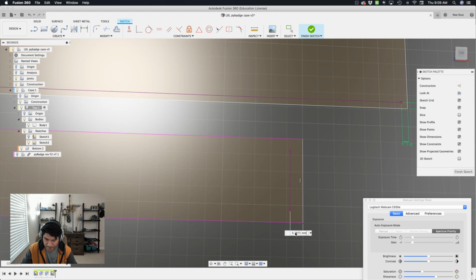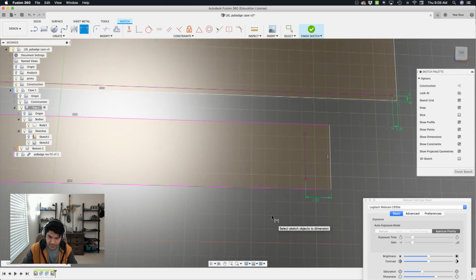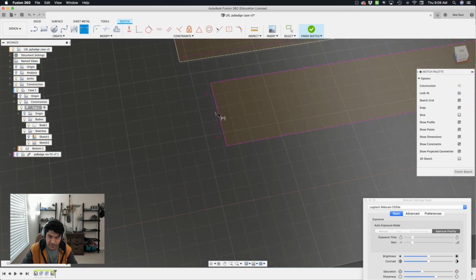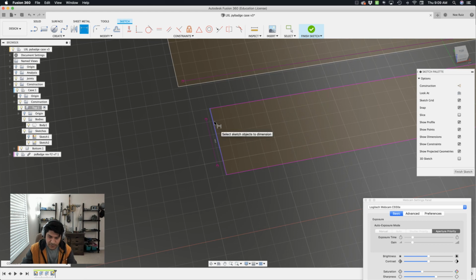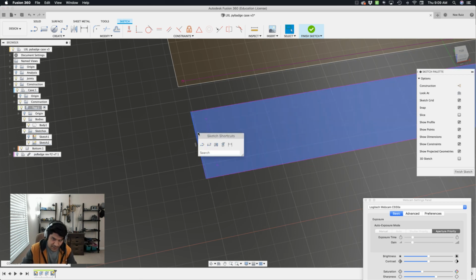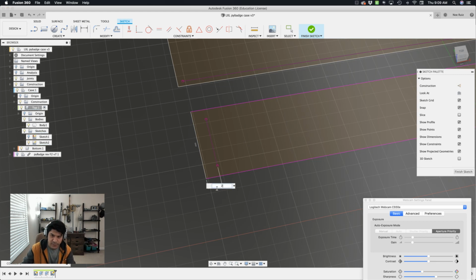Instead of using gap, I'm going to put in a bigger value. I'm going to put in 2 millimeters. And the reason being, because this right here, these two corners, I'm going to fillet them out. So I'm going to add a giant fillet. And when that fillet gets in there, you kind of want a little bit more clearance than just the gap, because you'll actually be kind of cutting into the actual neopixel element, the body of it. So let's change this tool because I need to actually push this further out, and then I can apply the dimension. And then the number was 2.